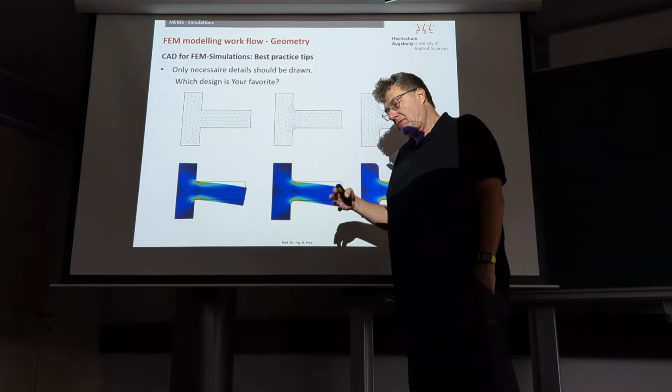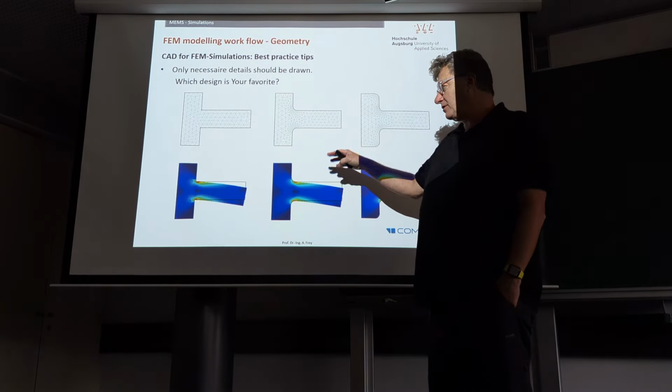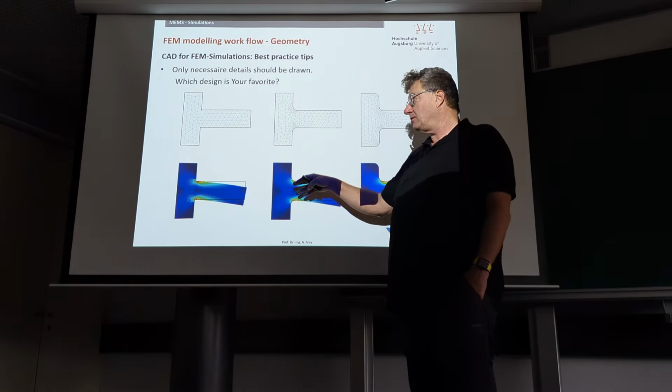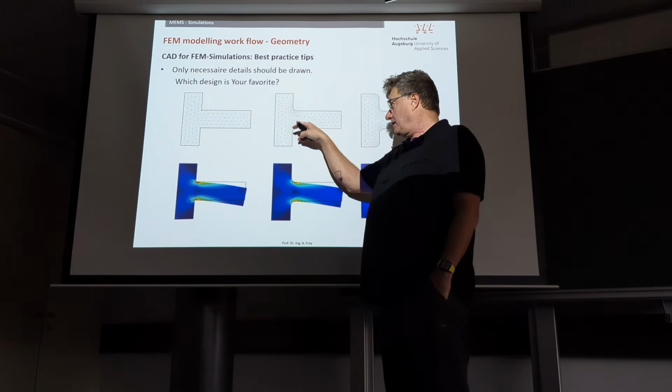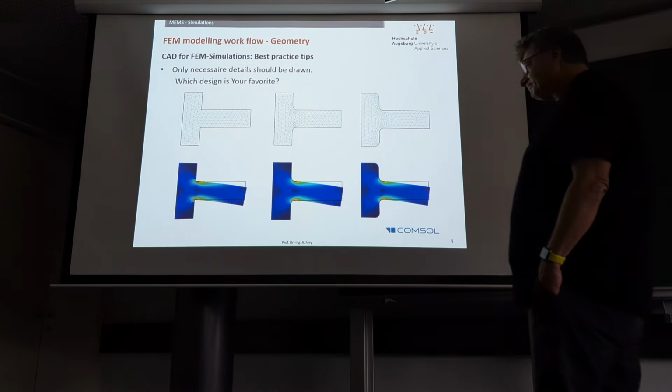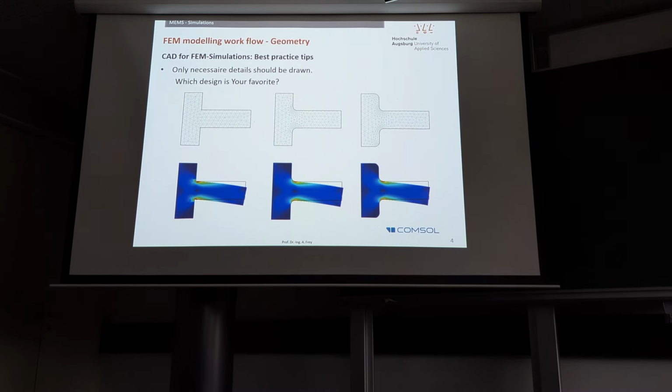That is kind of simple, so maybe you don't need a simulation for that. You know it anyway. These fillets are the most critical thing. So this is something where you definitely have to put a fillet in order to get realistic stress values.